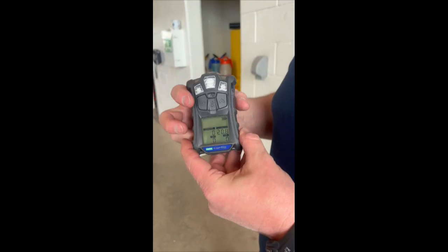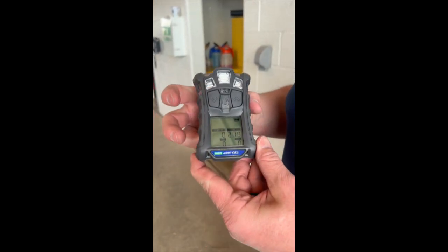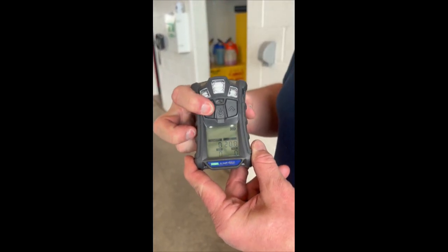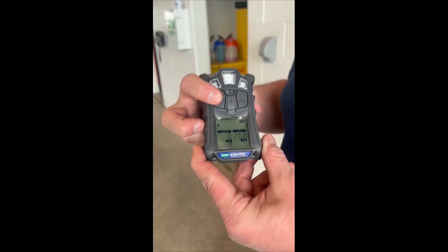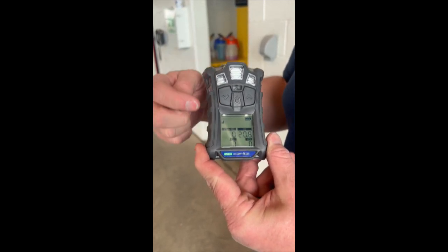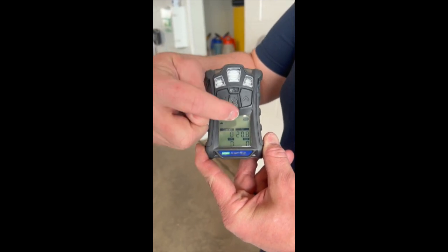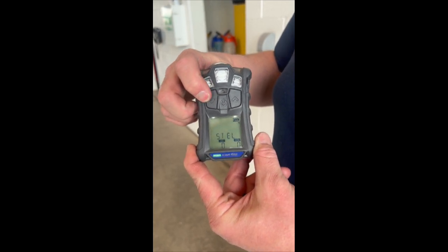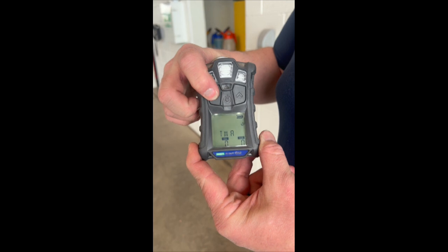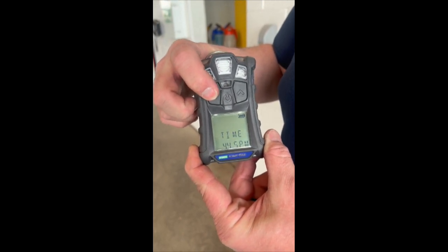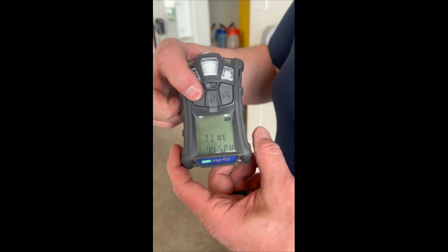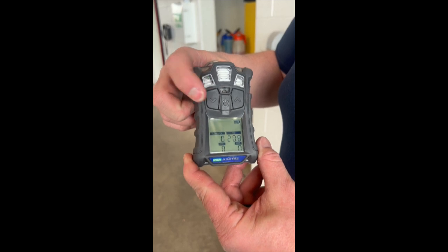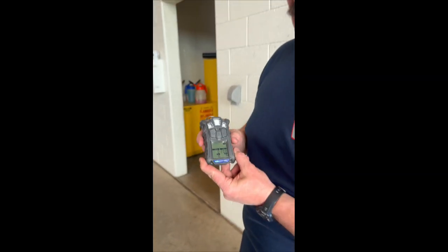To operate this unit specifically and to go through the different values, once you've gone past your startup stage, you're at your monitor screen. Clicking the down arrow takes you first to bump test. When you click it again, you'll notice a little mountain. That's your peak value since you've turned it on. Then your minimum, then your short-term exposure limit, time weighted average, and then through some just monitor documentation, the time, date, motion sensor, and back to your main screen.